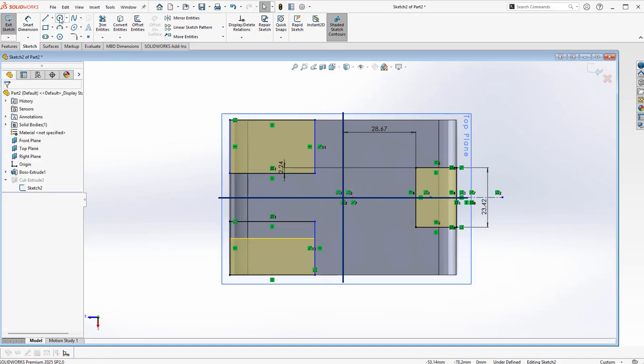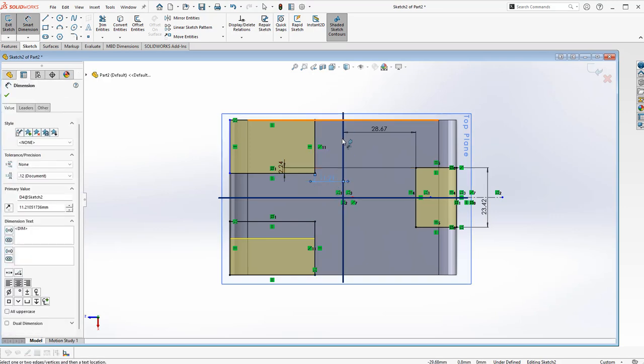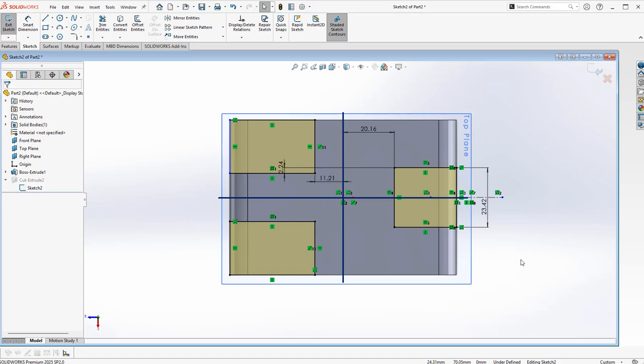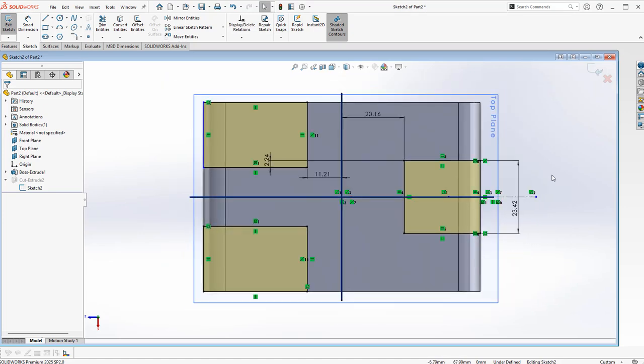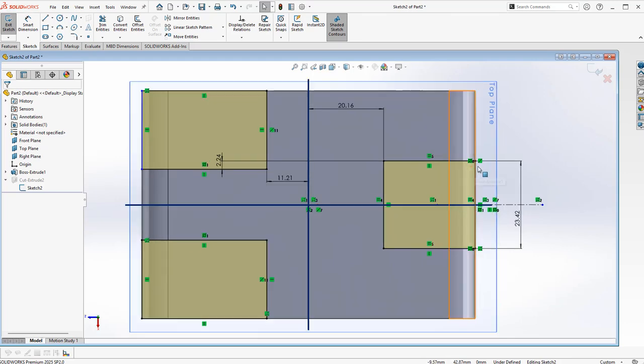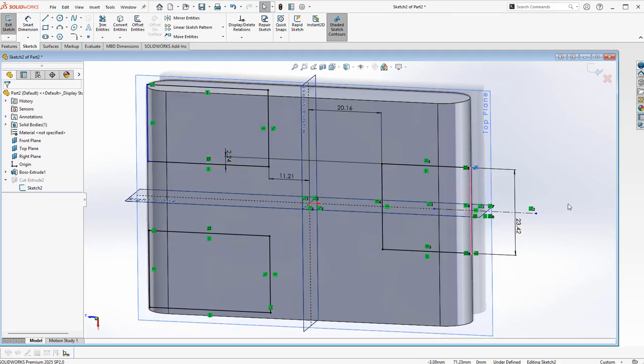All right, and how do you want to control this one? I can dimension it to the center. So after dimensioning it, what seems to be appropriate, we can come back and change our mind if we like. What I want to point out is this edge: when I turn this cylindrical face to an eyelet where it's got draft on it, this collinear reference or this coincident constraint is going to fail. And I think it's helpful to anticipate these failures.